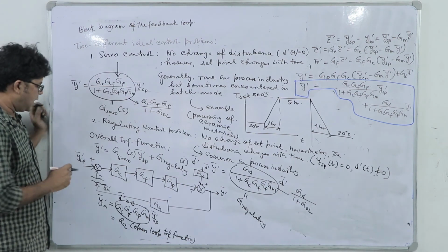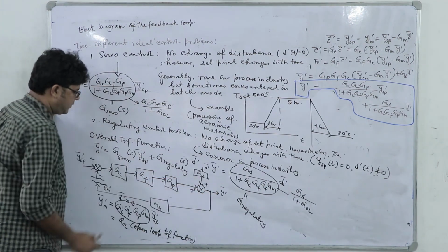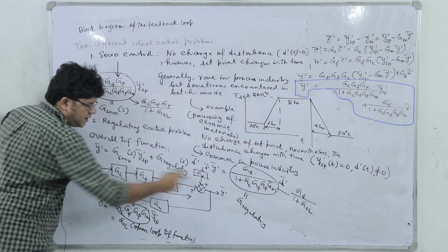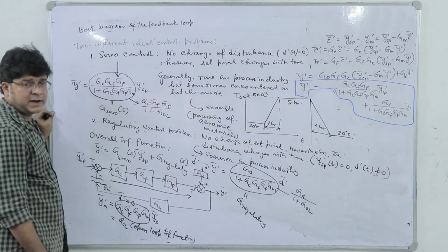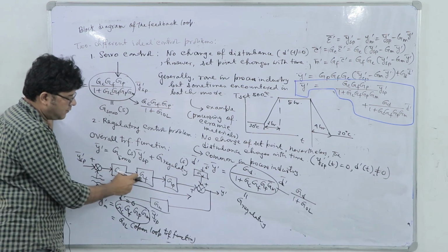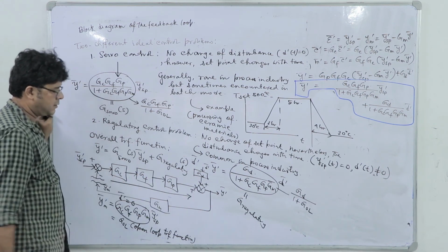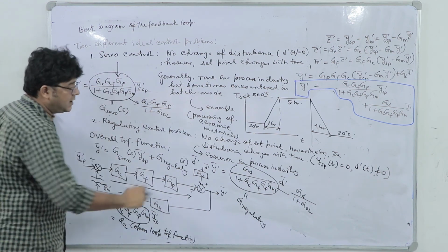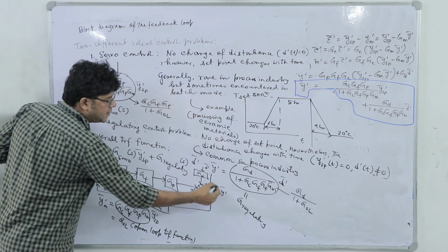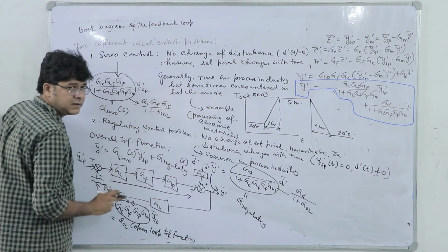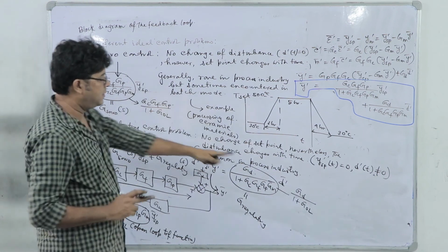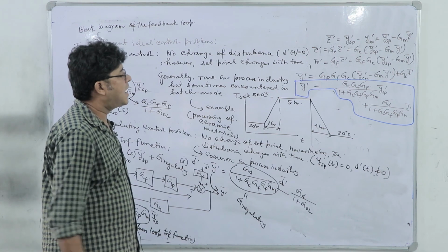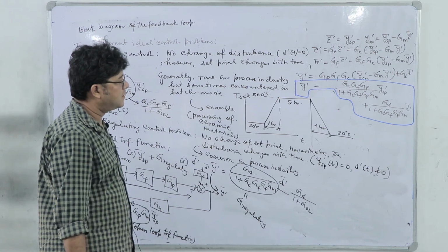Now you see, what about the numerator? In the servo block, we are relating Ysp to Y. If I move from Ysp to Y, this is the direction, straight out. How many blocks do we face? Controller block, final control element block, and the process block. We take the product and put it in the numerator. Similarly, when we move from Gd to Y, how many blocks do we face? Only Gd, only one, the disturbance block. We put it in the numerator. So that's the easy way of remembering the entire block diagram's transfer function.